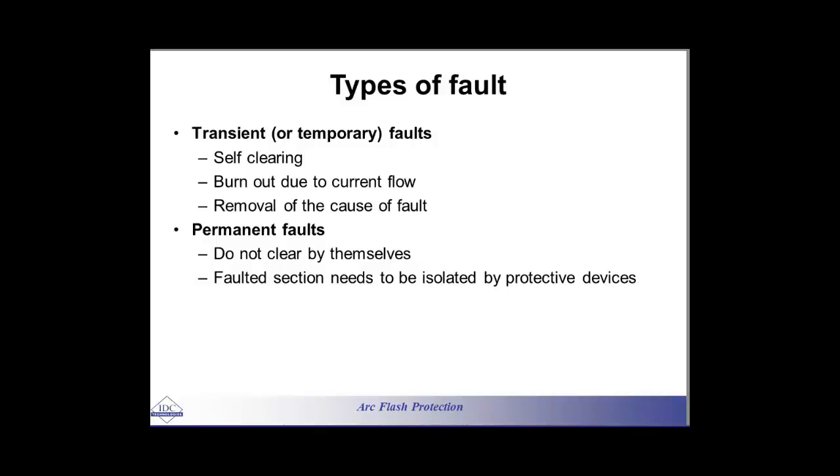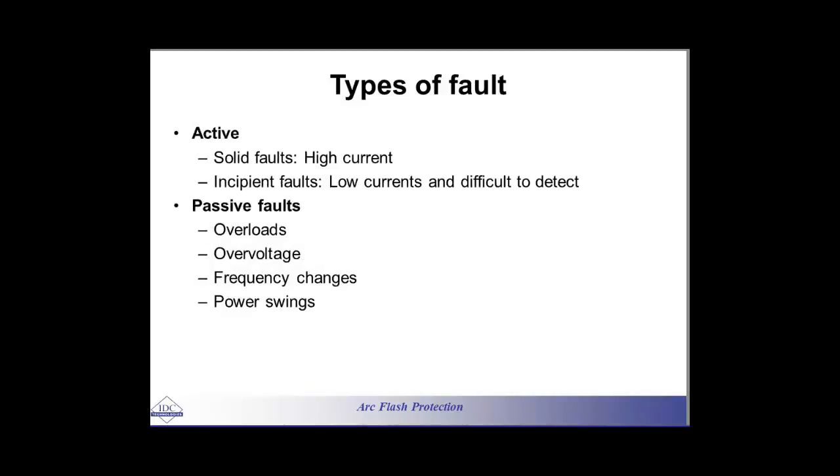So what types of faults have we got? You can classify the faults in many different ways. You can say they can be transient and permanent. Permanent, like, okay, you have got a puncture in a cable, that's it. You have got a breakage in a tower line, that's it. But sometimes it's transient, like there's a blow of wind, a strong blow. So just for a moment two phases touch each other, and that's all, and then everything is normal. So we have got transient and permanent faults.